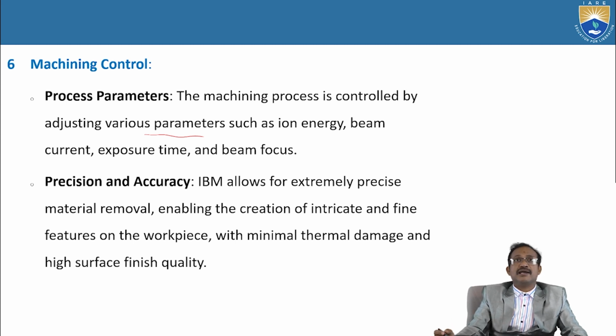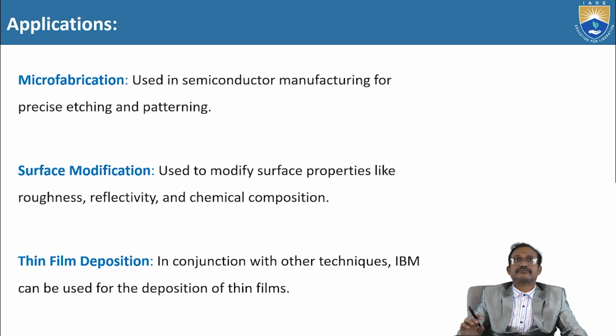So here along with the material removal, we should maintain freedom from thermal damage. There should not be any thermal effect, and also there should not be any heat affected zone near the striking over the workpiece material, in order to have good surface finish or quality.